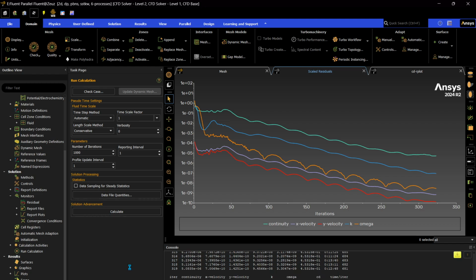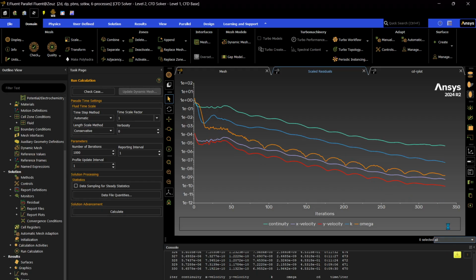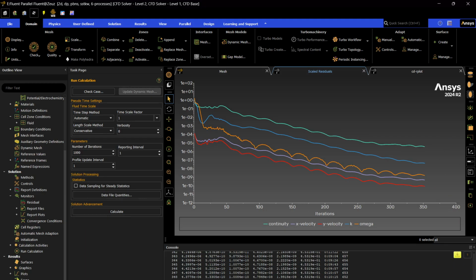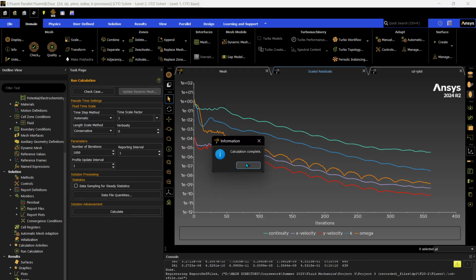Okay. I think I'm ready to say that it is converged. I'm gonna try to stop. Wait, it's gonna go lower. Okay. Yeah, no, I'm gonna stop the simulation now. It is a turbulence simulation, so you may not get the target criteria you want, but I'd say I'm pretty fine with this. I'm gonna stop it right now just to save on time. So looks good.